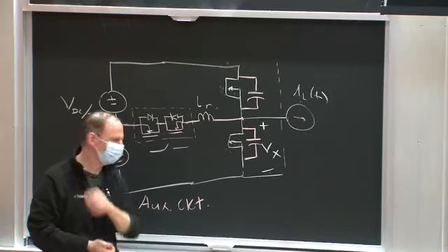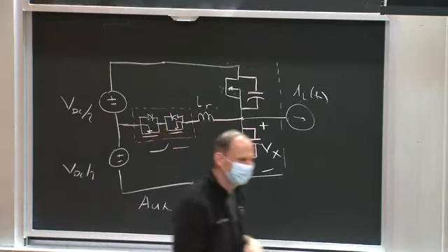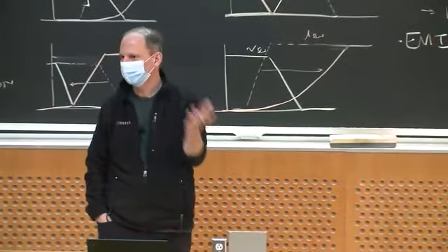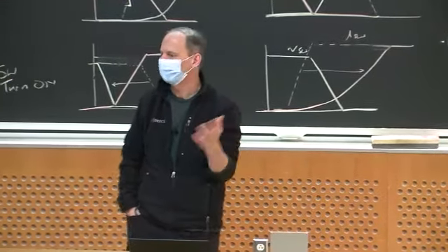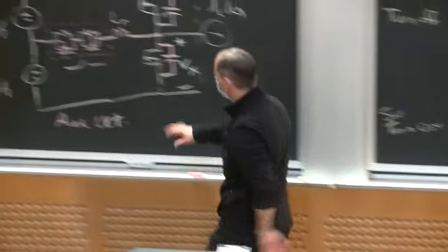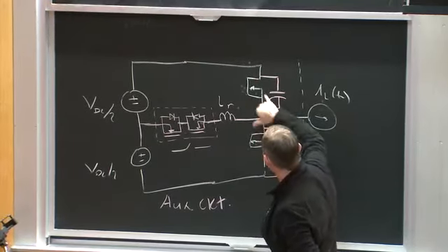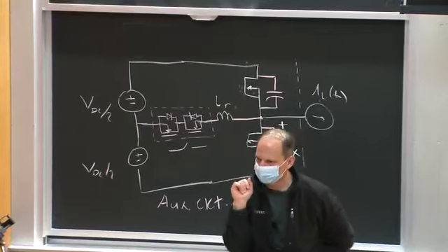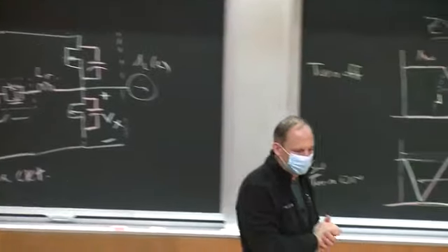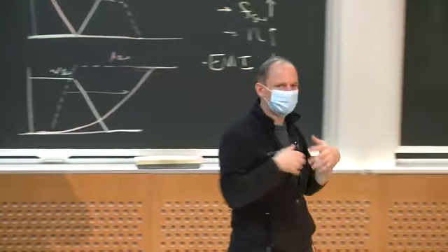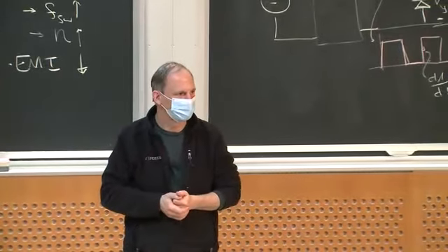Kind of. Now, let's talk a little bit after class. But yeah, the idea is to let voltages or currents ring up or down and then be clamped. In this case, it's clamped by this switch going naturally open. In the other case, the ring up is clamped by the body diode of the FET. And you go along that route. So that's a lightning introduction to soft switching.